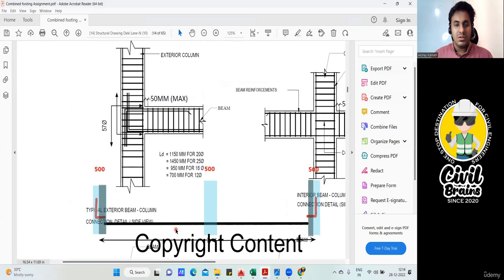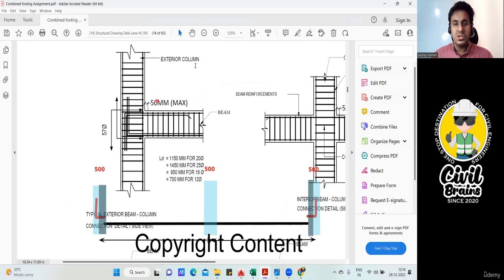Yeah. This is my typical beam column junction. So here they are indicating that this is your column, okay? They are indicating that whatever reinforcement you put in the beam column junction, this part will be your development length, measured from the inner face of the column, not outer, inner face of the column, to this complete L, whatever you have.